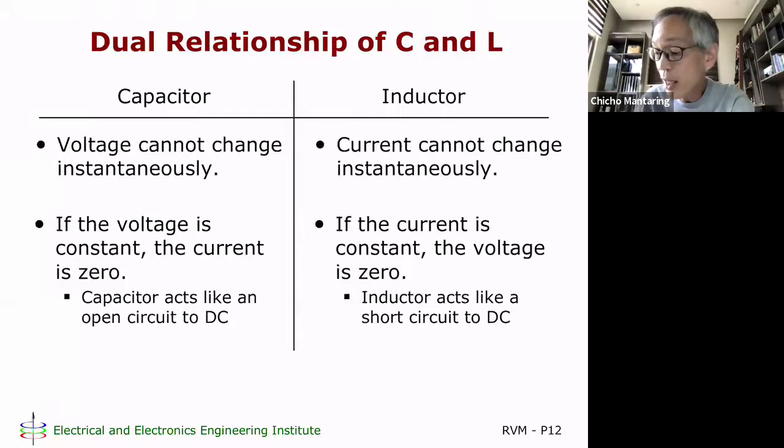And why did we not study capacitors and inductors? Because in a DC circuit, under steady state, your capacitor is really just an open circuit, and your inductor is really just a short circuit. That's why we did not have to study it sa DC. That's why all you studied earlier was just resistive networks. Pero magbabago yan, AC.